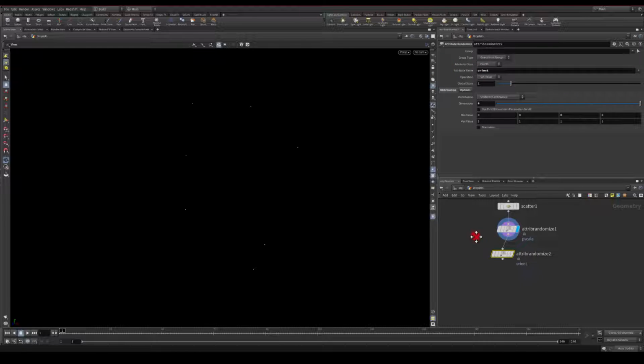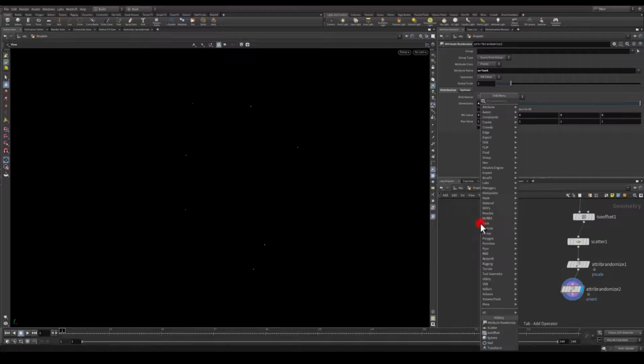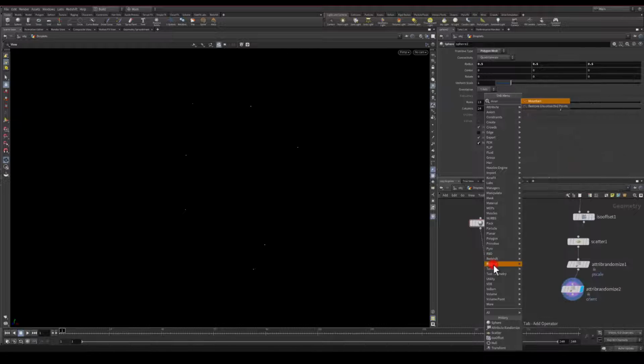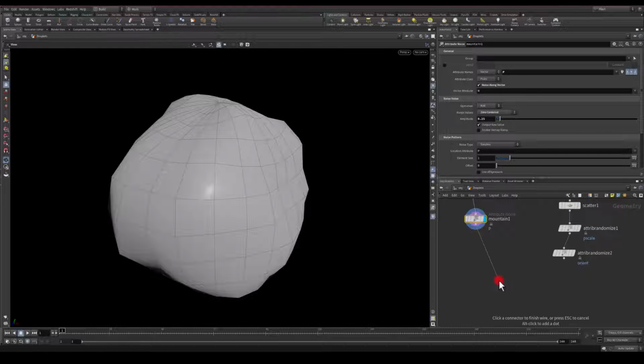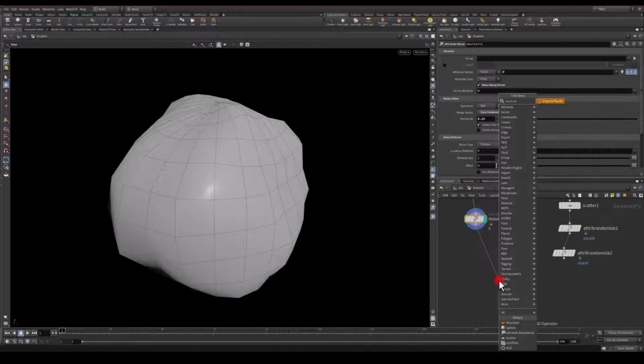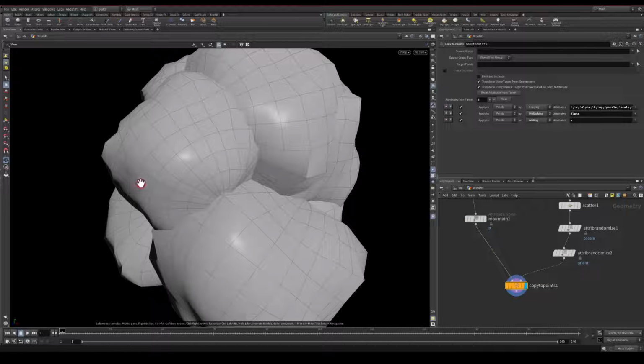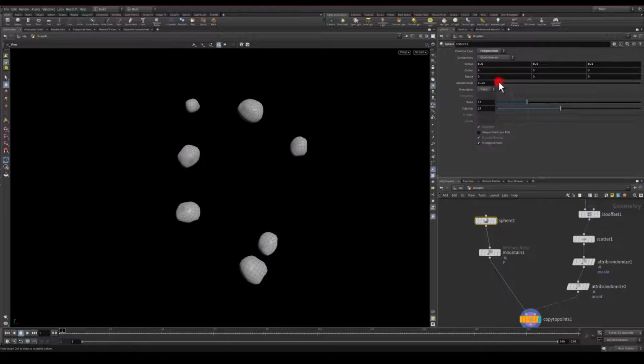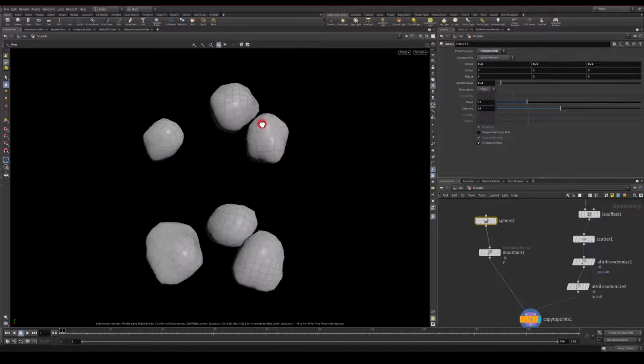We can't see it right now on the sphere because we're gonna be creating a simple sphere, so it doesn't matter its rotation because this is a random rotation orient, and it operates with 4 dimensions. So there'll be a vector 4. And here I'm just gonna get a sphere. I'm gonna get a mountain. And actually let me do copy to points. And let me scale this back down so we can see, hopefully, and they got slightly different rotations, exactly what we want.